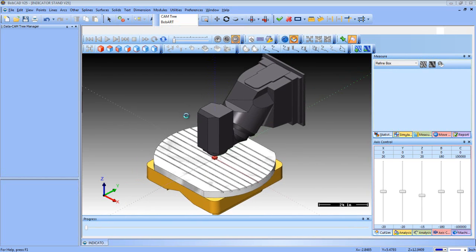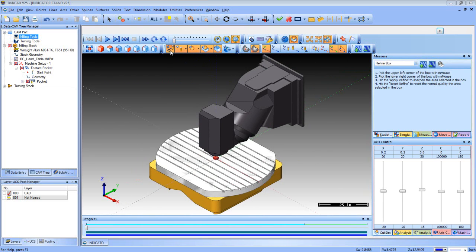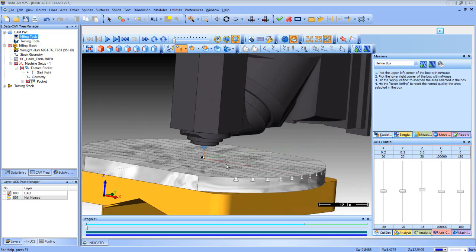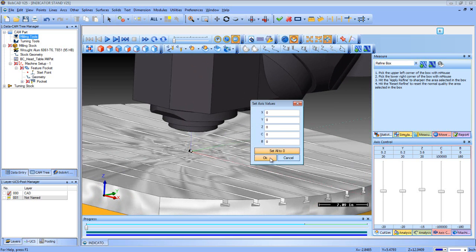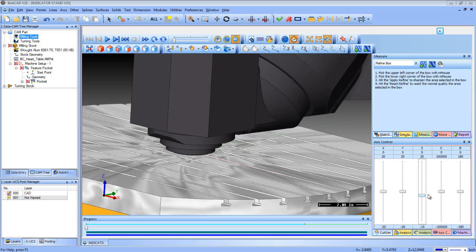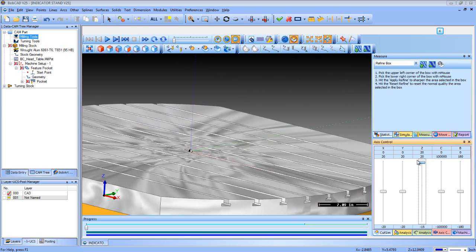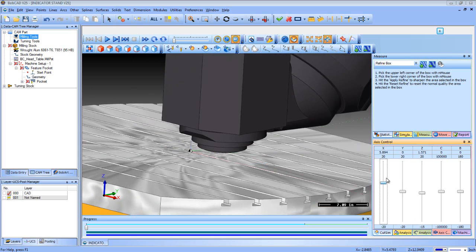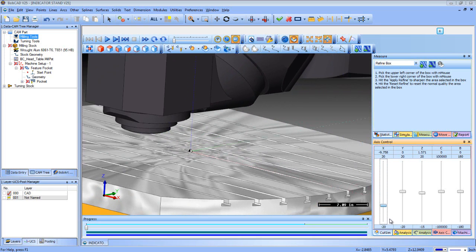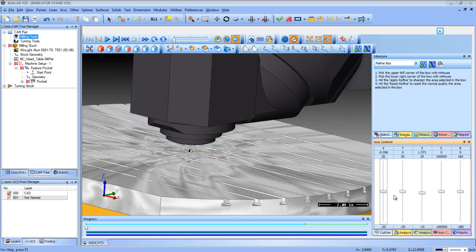So when this loads up here, what I'm saying with this one is if I turn all this off, all right, and if I zero all of them, see how it just brings the face right to the table? So you want to record in Z the farthest distance up from that position and how far it can travel down. Of course, virtually into the table you'll want to know. The same with the X, how far positive from that position and how far negative, and so forth. And record those numbers off of the machine.